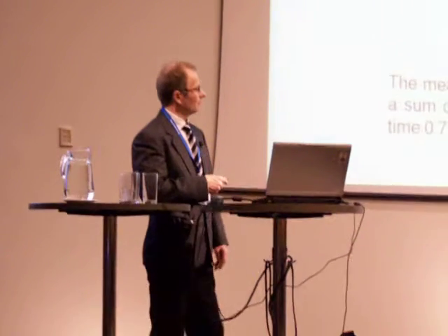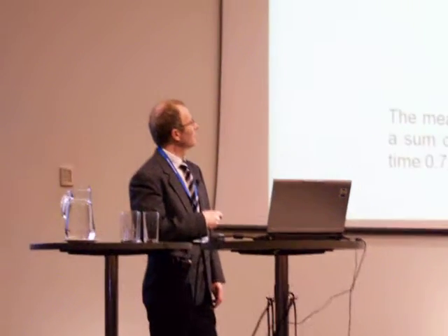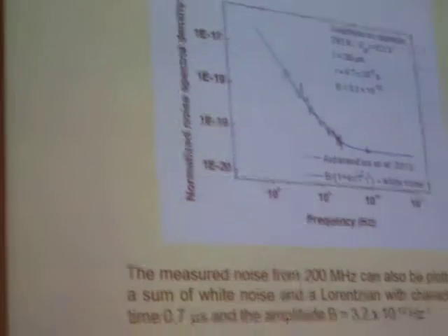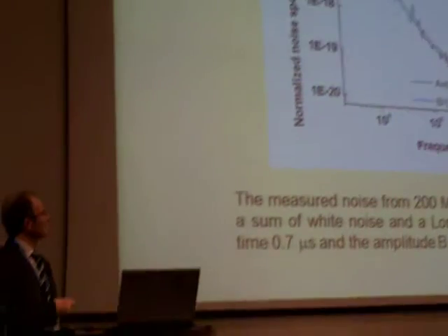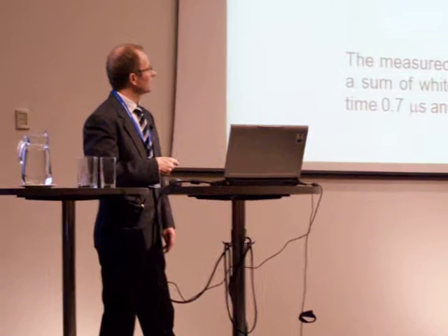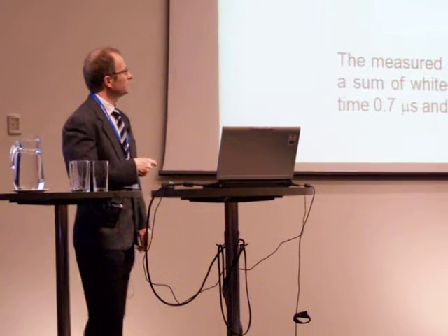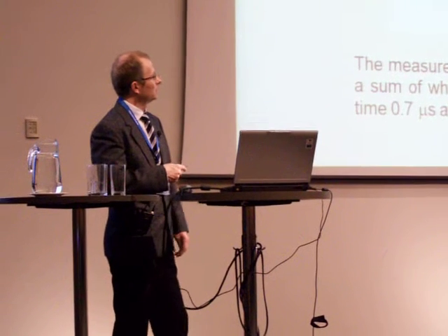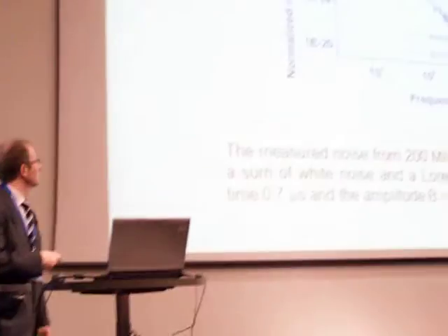It is worth noting that this Lorentzian can be explained by shot noise as a result of contact barrier resistance, which is shunted with barrier capacitance. At 10 GHz, this noise source is eliminated.